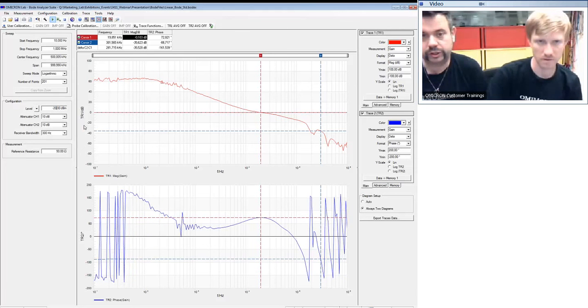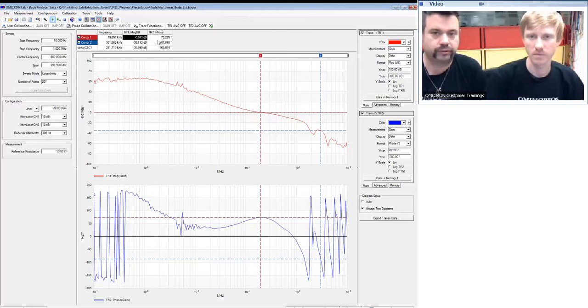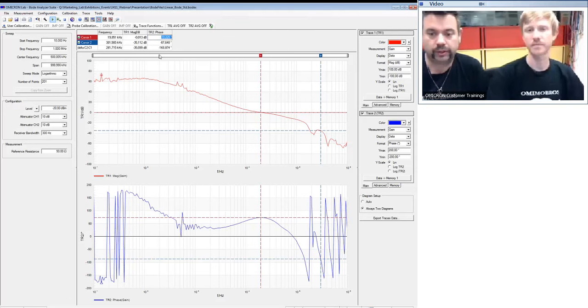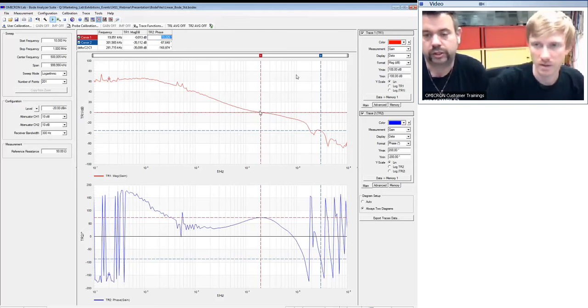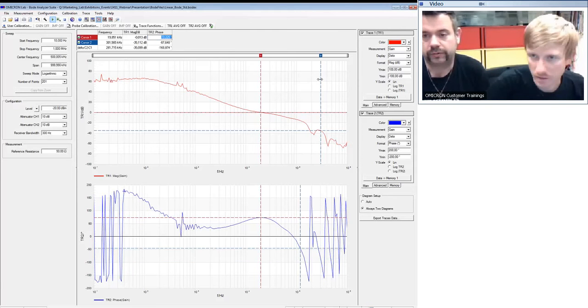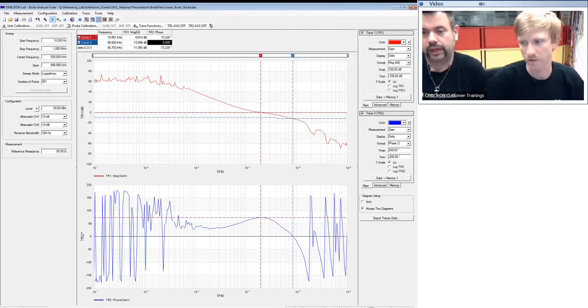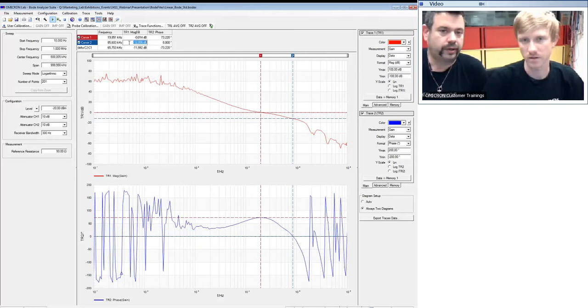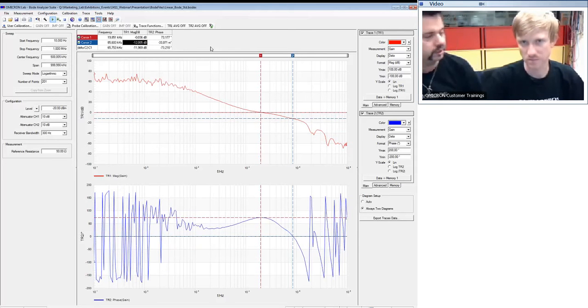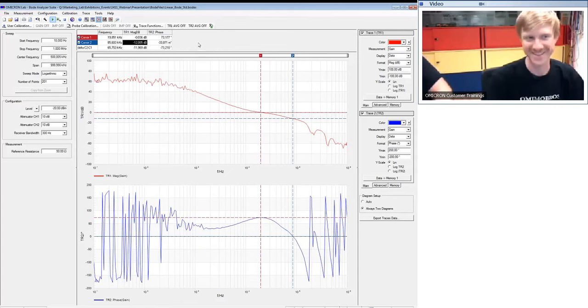Our phase margin is here 72 to 73 degrees, and we are also able to measure the gain margin by referencing to the point where the phase becomes 0. And here we can measure a gain margin of about -12 dB. So Florian, gain margin -12 dB, phase margin 73 degrees. Is this a circuit you would trust? Is this fine for you?